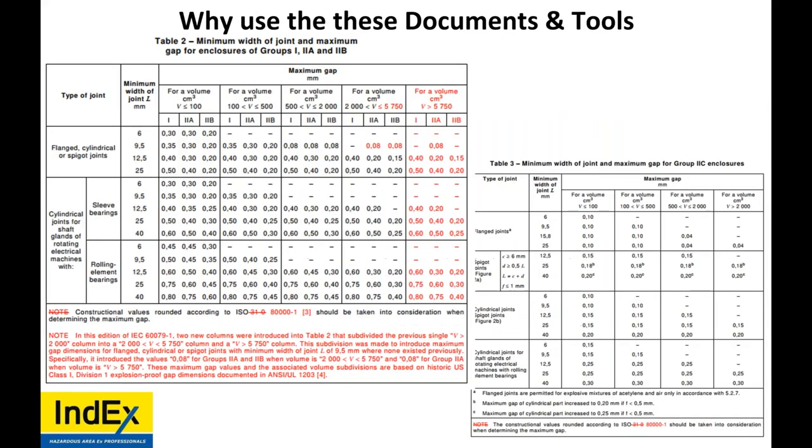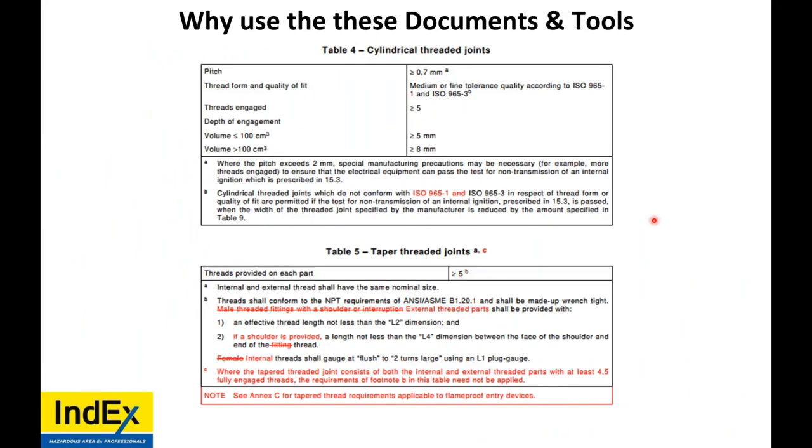Now, going by opinion doesn't mean anything. With those tools, you can at least verify with use of the certificate, IOMs, and standard with a legitimate tool that has been calibrated. So cylindrical and tapered threads. There are other considerations. Be aware of this. Inspectors only work to 60079-14 and 17.